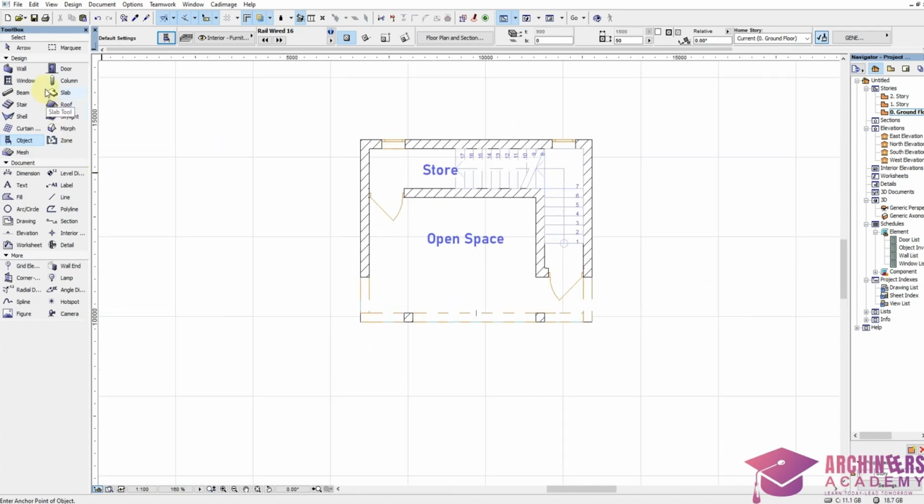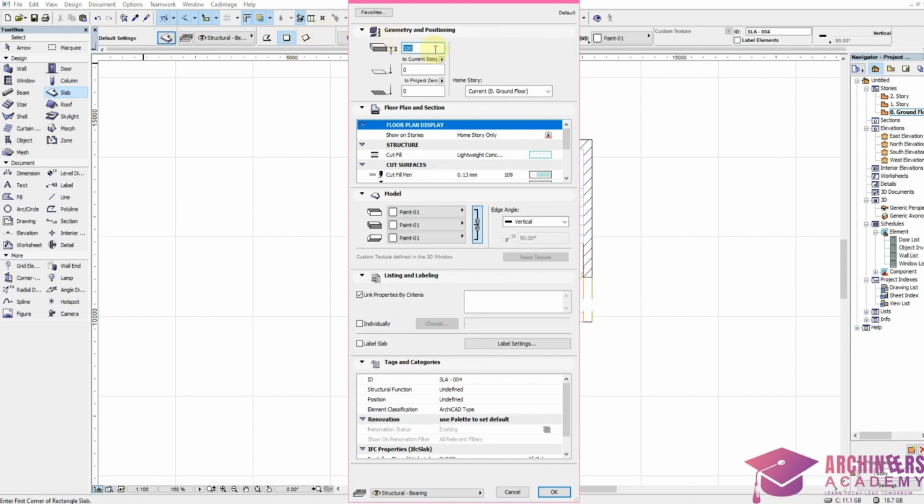So we'll come over to slab. Click here. Now remember, each riser is usually 150 mm on a standard note. But now we are creating the step individually. So right now the thickness will be 450 because the DPC thickness is 600. If we're stepping down, the next height will be 450 because I'm subtracting 150, which is minus 150.